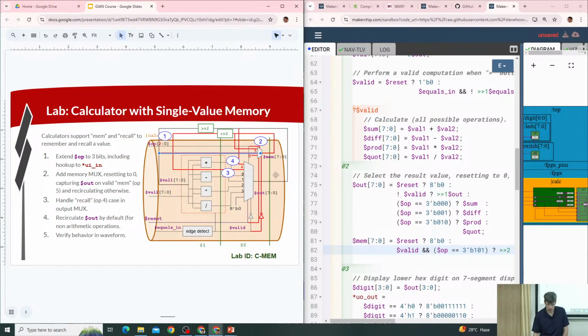Taking the value from the output mux, but with a 2-cycle delay. So I'm taking the value from the output mux from the operation that happened 2 cycles earlier in the pipeline. So that means a reference of ahead by 2. And this is from out.